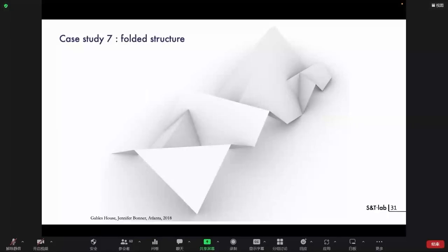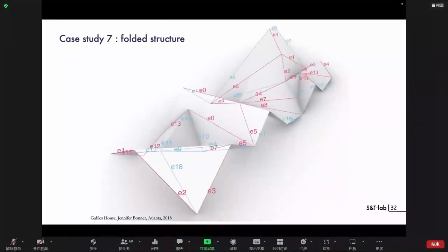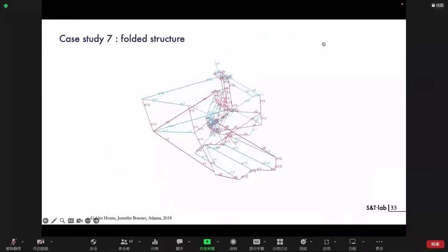We can parameterize it in Rhino and run some analysis on it with VGS. You can see that it's quite a complex equilibrium that gave me some headaches to achieve, but the folded plates of CLT panels just appear in the analysis of VGS. We can see the ridges in tension and the panels with diagonals in compression, or the opposite from one side of the building to the other. And this was the form diagram.